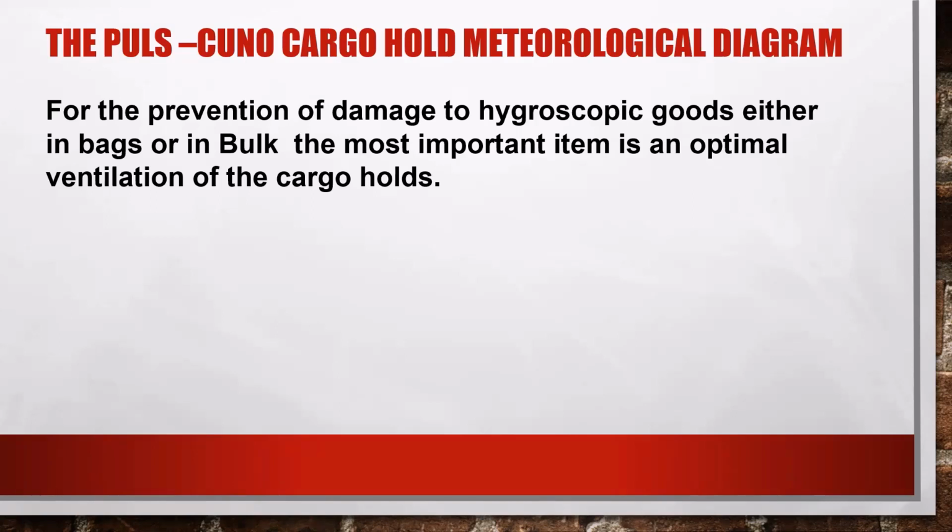for the intended voyage, especially if we are carrying special hygroscopic cargoes like grain, or, for example, steel cargo, which also has to be correctly ventilated if we have to ventilate the cargo. What has to be on hand to analyze what is required is the temperature: the outside air temperature, dry and wet, and also the dry and wet bulb temperature from the cargo holds. Those are the requirements for analyzing if I have to ventilate or not.